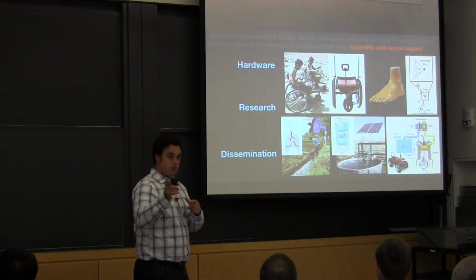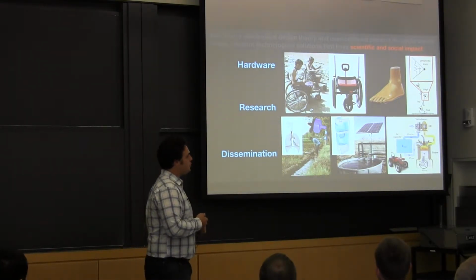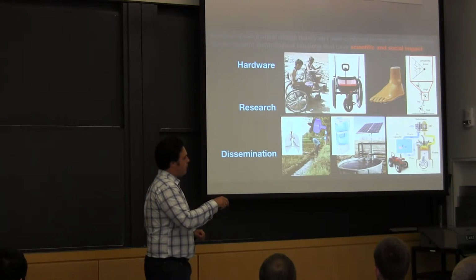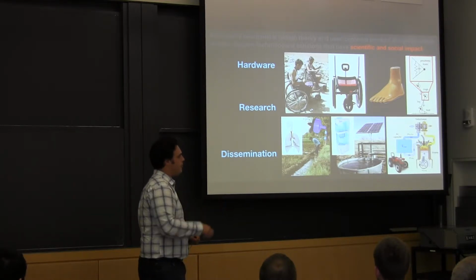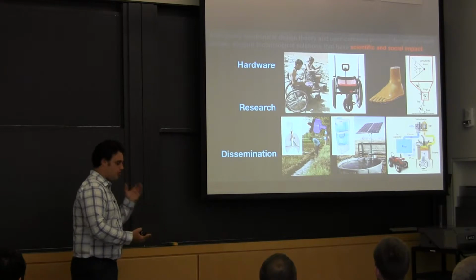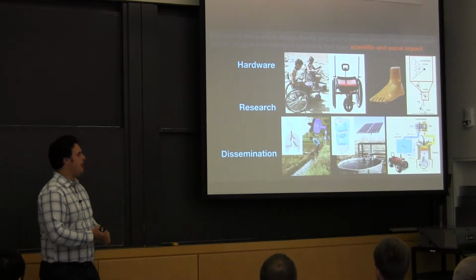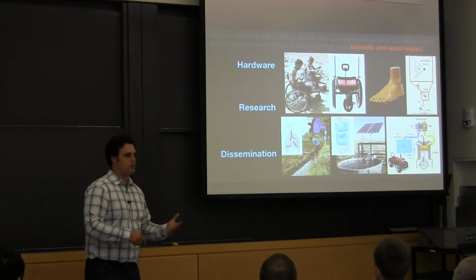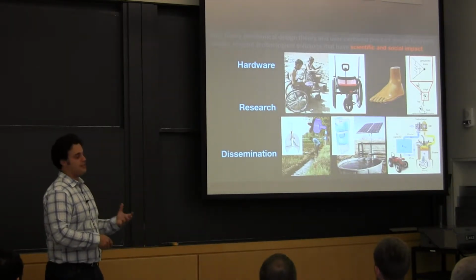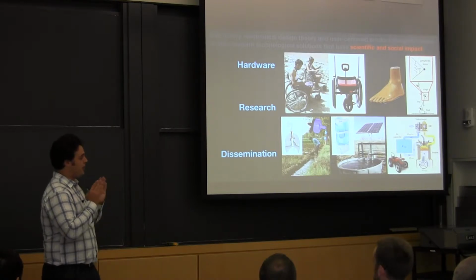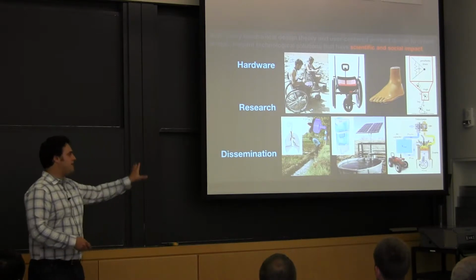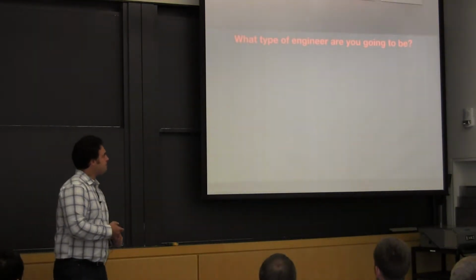And then finally, Michael's project is working on a means of turbocharging single-cylinder diesel engines by adding, here's the engine, here's the turbocharger, and adding what we call an air capacitor as part of the intake manifold. And what that does is allow you to add the turbocharger, make more power, make a more efficient engine, and that could have big ramifications for applications like tractors, water pumps, rickshaws, generators, tons and tons of applications in emerging markets that currently use naturally aspirated and thus less efficient single-cylinder engines. But anyway, that's kind of the portfolio of what we do.